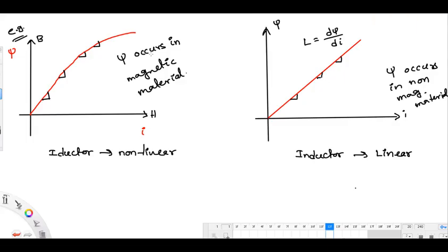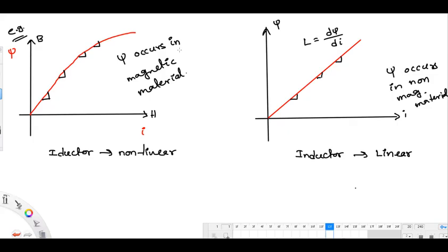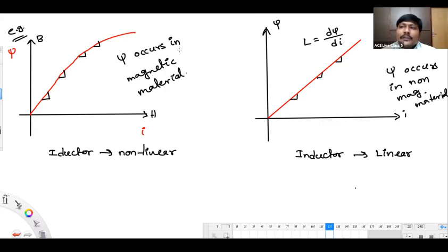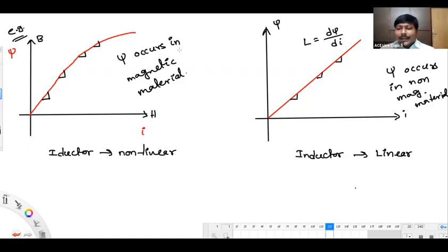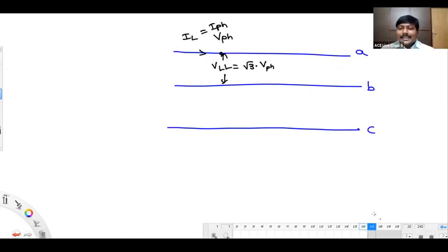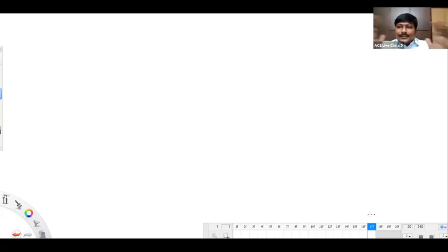Tell me, Haripriya. In yesterday's class, why do we use hollow conductors on bus bars, sir? I mean, current rating, to reduce corona. Sir, in current rating and radius, how are they related? Proportional. For high current, radius must be high, sir. If you want to send high current for a long amount of time, the radius of the conductor required should be high. How, sir? You should go with basic analysis of current flow. Very simple. If you want to pass more charges, you should offer more cross section, right?